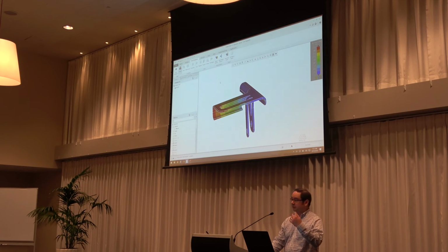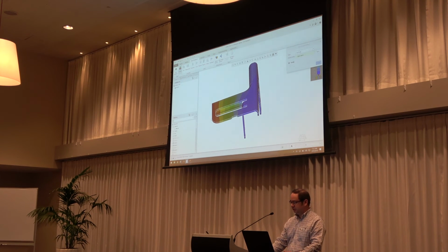In the video, we saw simulation probes, so you can create them if there's a particular area you want to look at as you change things. So I've got those simulation probes, again, just using the same sort of Creo UI for that. I can pick a point and then keep that probe there while I look at my different design changes, okay? So that's simulation live in its essence, okay? The beauty of it is, as I said, for the Creo users here in the room, it's completely embedded inside, so the workflow is much, much simpler. No sending data back out and coming back in, okay?